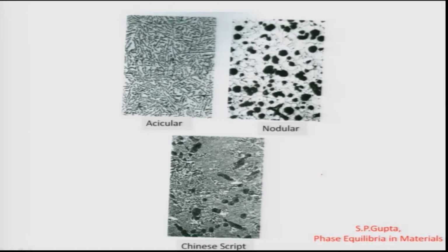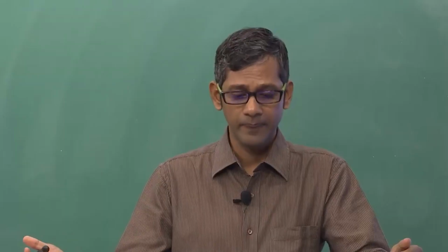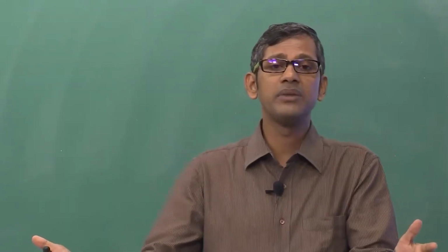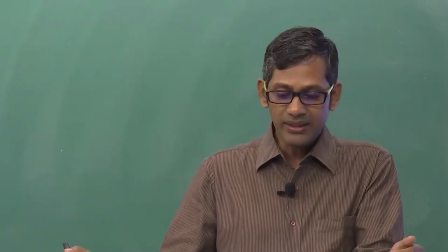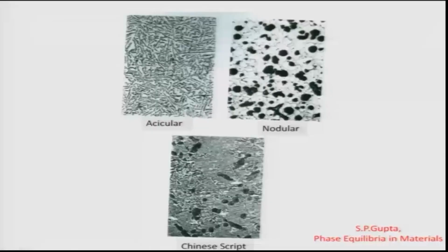Aluminum-silicon, which I discussed in the last class, is also a very classical system, because these eutectic alloys are used in industry, for example in cylinder blocks of many car engines. The eutectic morphology is known as acicular. The continuous white phase is aluminum solid solution, and these long fiber-like features you see here in black color are basically pure silicon fibers.